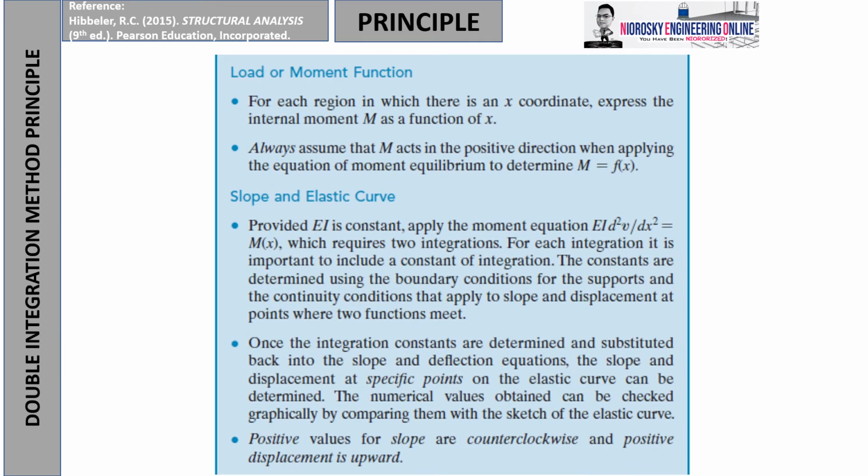Okay, ganun din, you have to write the moment equation. However, the moment equation should be continuous with respect to the cutting plane. Ang gagawin po natin is ganito, para to simplify this rule. Kahit may overhang ka man o wala sa dulong kaliwa, what you're going to do is this. You always get the leftmost part, whatever the location, kahit may support o wala, and set that into a y and a coordinate of x-axis, where this will be the 0, 0 coordinate. And of course, the supports will follow, statically determinate or indeterminate.